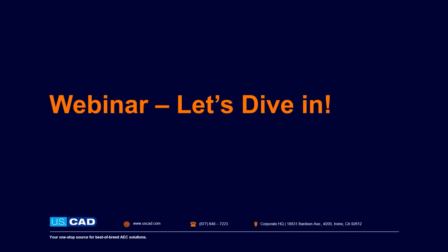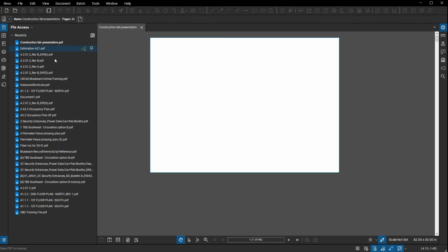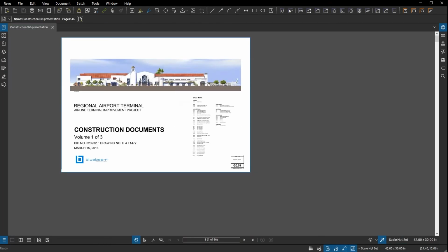So, diving right in, I'm just going to go right into the software. So here's my Bluebeam Revu. Pretty straightforward. One of the first things I like to go through with the PDFs I've been given is to verify it meets your requirements. There are certain factors you want in place when a file's been submitted to you for permitting, just to make your lives easier. One of the first things I like to look at is how the PDF has been labeled.